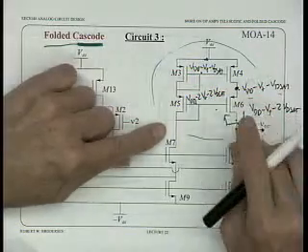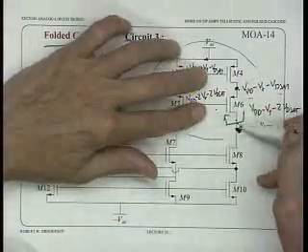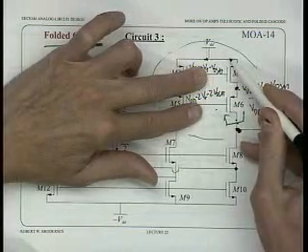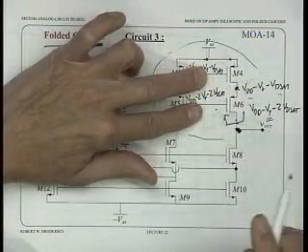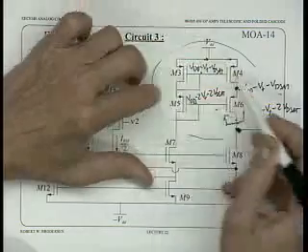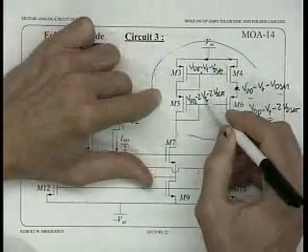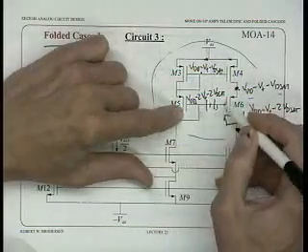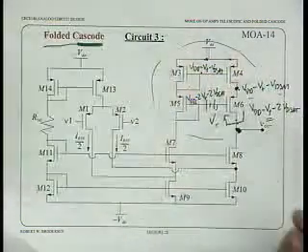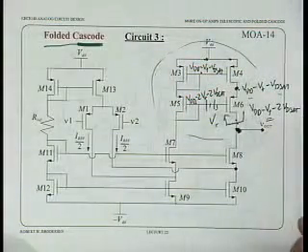We know if we have high swing that we should be able to get within a VDSAT of this VDD. We got the VT still sitting in here yet. So this is not biased in the high swing condition, right? How do we do that? Well, we could drop this down by a VT somehow, or there's some other circuits that I'll show you in a second. Okay.